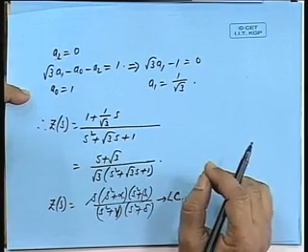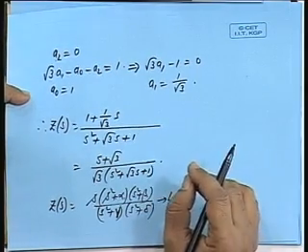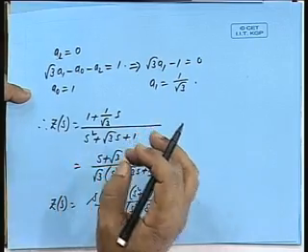If the first root, nearest to the origin, is a zero, then it will be an RL function, and we can realize it again by 4 canonic forms. Suppose it is a positive real function, but roots are not alternately coming, then it is neither RL nor RC, it will be an RLC network.